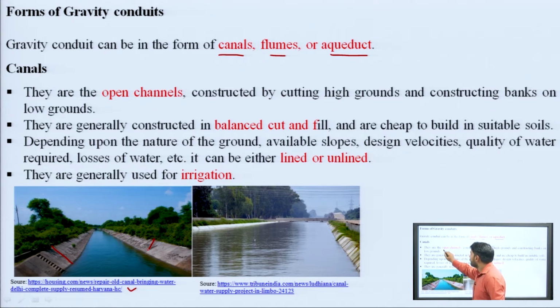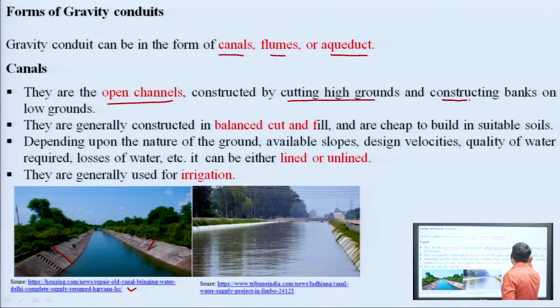Canals are open channels constructed by cutting a high ground and constructing banks on the low ground. There will be two possibilities. If the ground is at a certain height, then we have to perform ground cutting, and if the ground is at a very low level, then we have to fill it, which means we have to perform both cutting as well as filling.